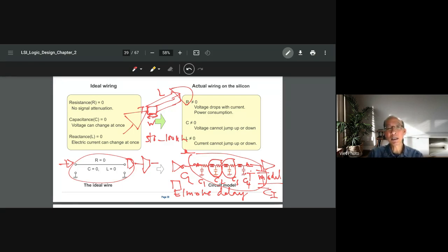The implication is that when the width is bigger, the resistance will be lower. The resistivity will be lower. Now the width goes down to only 10 nanometer, and the thickness goes down to about 10 nanometer too. So you have a reduction in two ways, the thickness and the width, which is like a double, exponential. Which means now the resistance is very high. And then resistance increases.